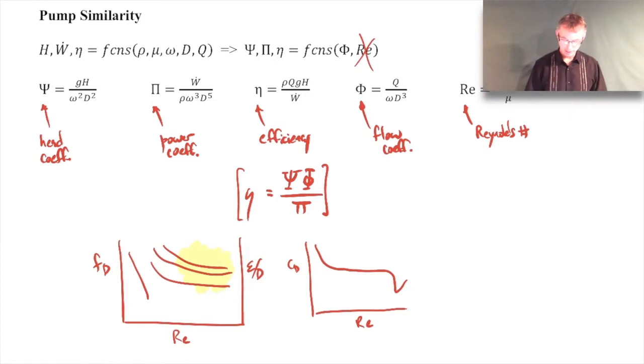So instead, these things are a function of the flow coefficient only. Okay, so then if we want to do some scaling, if you remember back from your dimensional analysis work, we just need to make sure that we keep these dimensionless terms constant from one scale to the other scale, and then we can just do scaling from our pi terms in that manner.